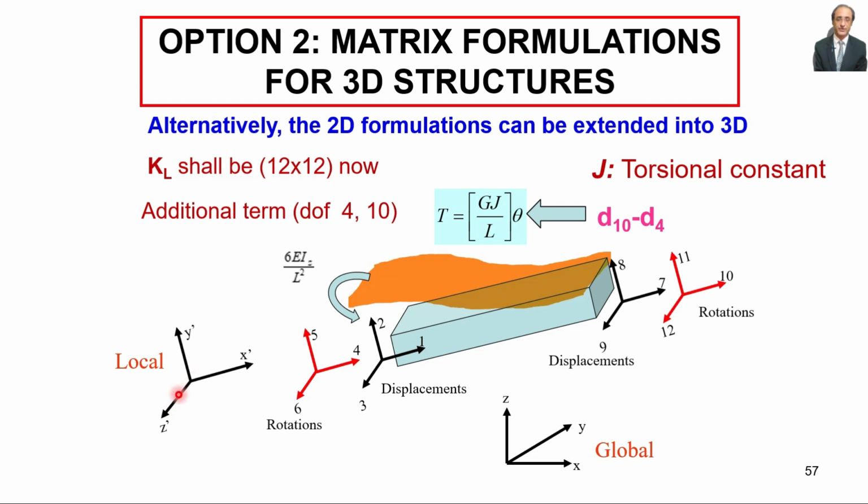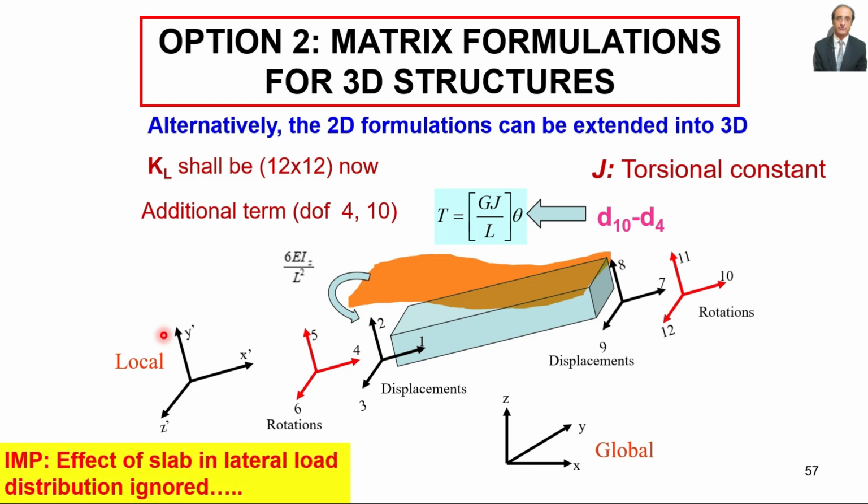Similarly, if the member undergoes displacement along the degree of freedom 3, in that particular case, the moment would be generated about the local y-axis, and here instead of Iz, Iy would be invoked. So this must be taken into consideration.